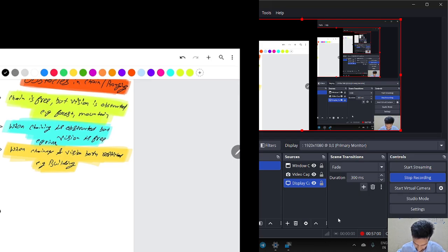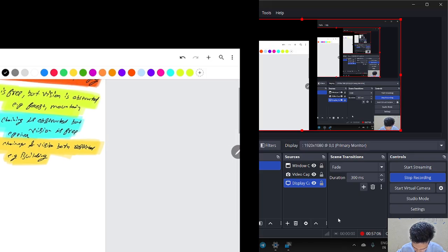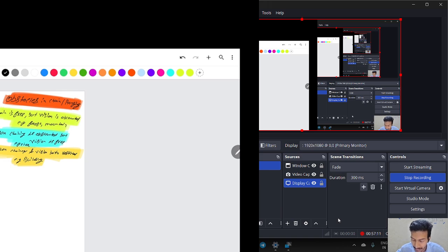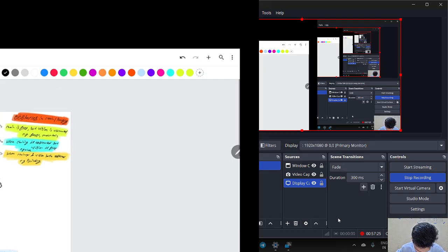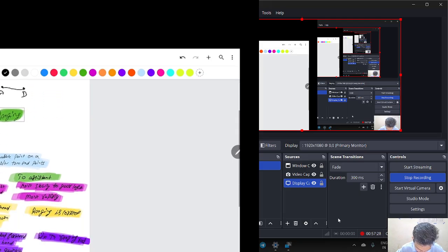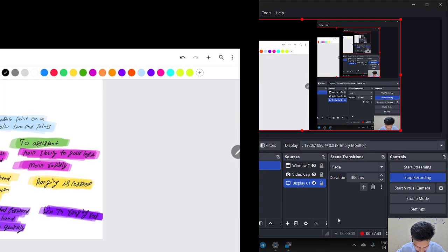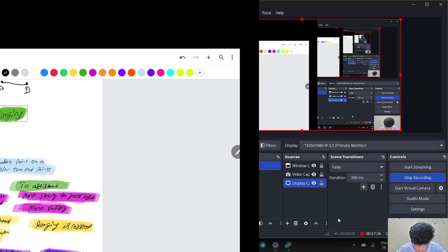And the last one is when chain and vision are both restricted, like an obstructing building or structure. We can't see and we can't move the chain to measure inside. And the last is to establish an intermediate point. What is ranging? Ranging is known as establishing intermediate points on a straight line between two endpoints.